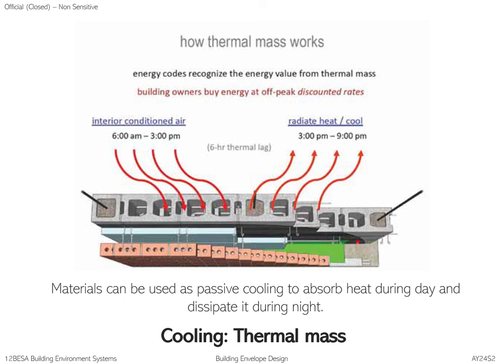You have the waterproofing that's painted. That should be a PVC-L plate. Then you have your heat insulation, rock wool insulation in between, and then you have the air gap cavity for the air to move within the wall itself. Because when the sunlight hits the wall, it warms up. So within the wall itself, you also need to cater for vents to ventilate.